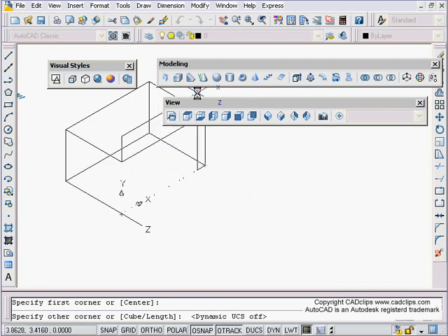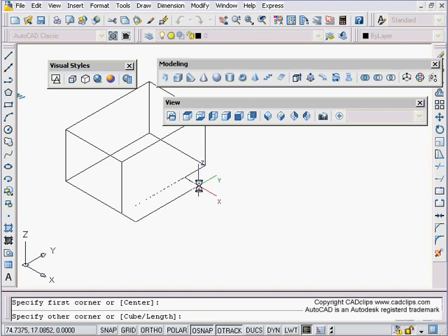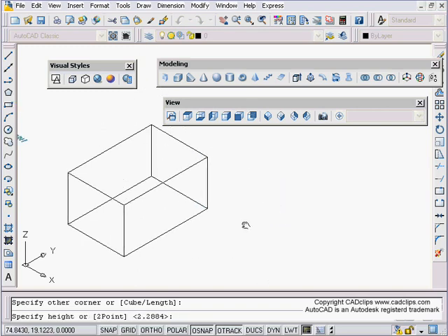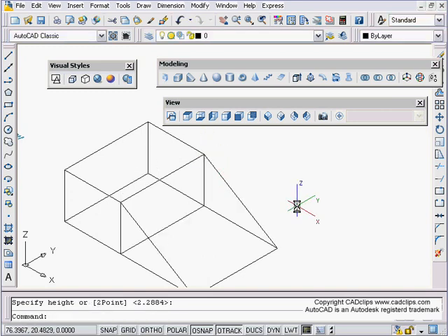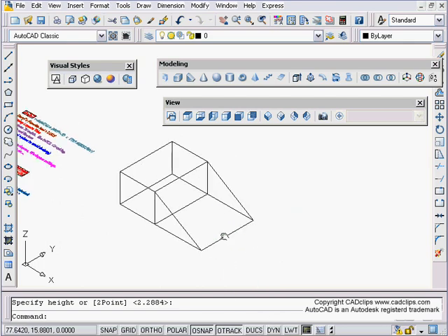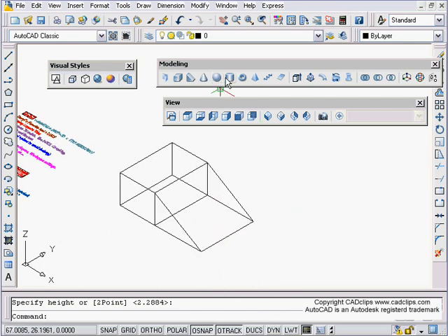I don't need my DUCS for this one. Wedge from here. Notice it started to draw up the side of that wall. Click. And now I can go pick that endpoint. Okay, I had to turn my DUCS off because the purpose of DUCS is that I can do this.